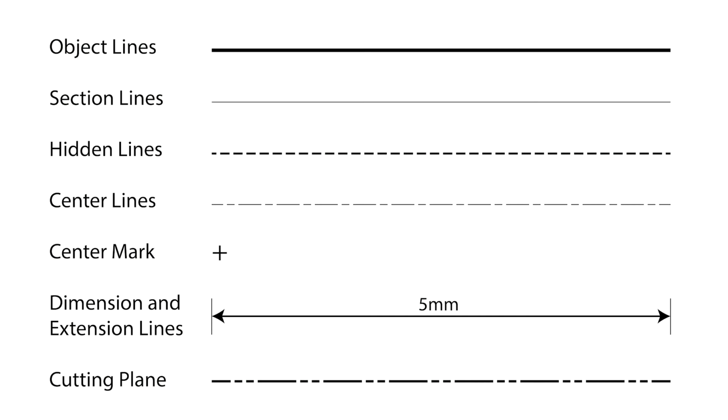Different line types are used to improve the meaning of a drawing. Thick lines are used to draw the outline of an object. Continuous thin lines are used to show dimension lines, extension lines, and leader lines. Hidden lines are used to explain hidden details, and center lines are used to indicate the center of a circle or an arc.